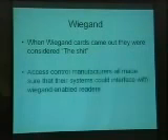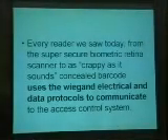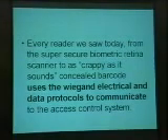Wiegand cards, the bollocks. These were the most secure things ever when they came out, back in the 60s, 70s. And all the access control manufacturers said, right, we want that. Wiegand didn't make access control systems, they made the cards and the readers. So basically, everyone wanted to interface with Wiegand readers, and they still do. So everything we've just talked about, from the retina scanner down to your standard prox swipe, all use the Wiegand electrical protocol and the Wiegand data protocol to signal back to the controller.